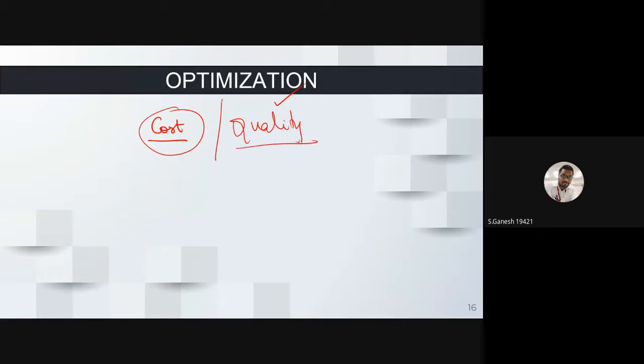So how this optimization is based on cost and quality is how you make a section designed properly. What kind of iteration level do you do? Practice with different types of load patterns. You come to know, yes, in the previous model I did on this part, I got a safe limit. So why not go to the second project with the same model? Loads are different. Okay, so this size is not suitable for this particular load, so I redefined my size. So I come to know that for a certain set, this size is suitable for this particular range of loads.